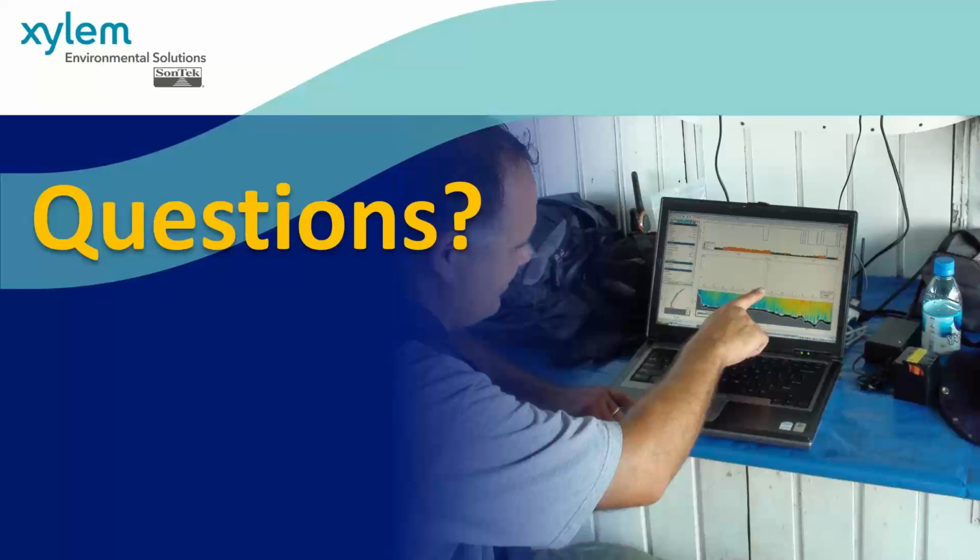There is a setting for the M9 in particular. If you go into your utilities software, there's a setting for low, medium, and high radio power. So if you do notice that for whatever reason you're just not making the distance that you expect, switch it to high power. I know there are some countries and regions where that high power might be problematic, so just make sure to check your local rules and regulations before you use that. But that's something to try if you're really struggling with communications. And then of course, make sure there's no rust or corrosion on any of your connectors to make that intermittent.